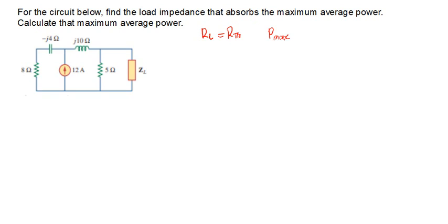So now, we are going to use a similar concept here. Another thing that I would want to put across is that when you're maximizing power, it's just a matter of matching the circuit and load impedance. You have your circuit impedance, which is the Thevenin impedance, and you have your load impedance.